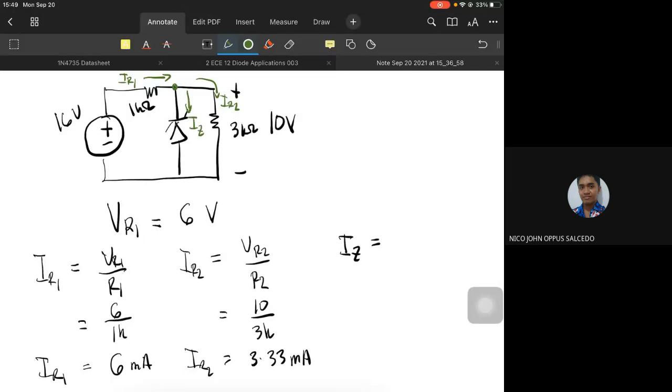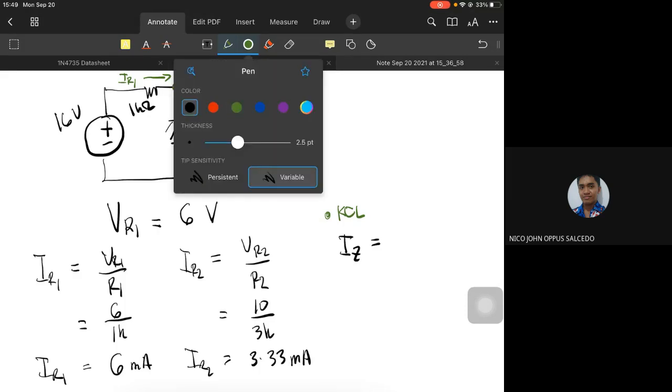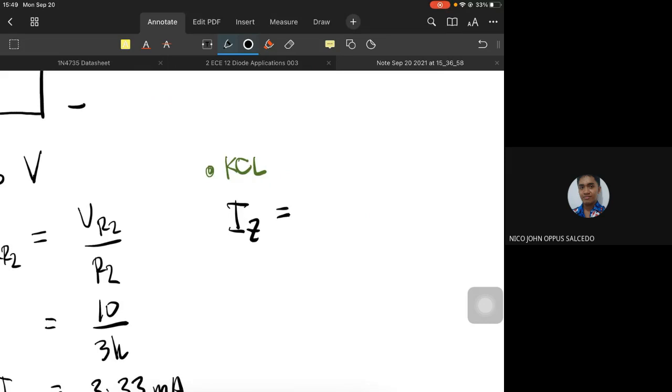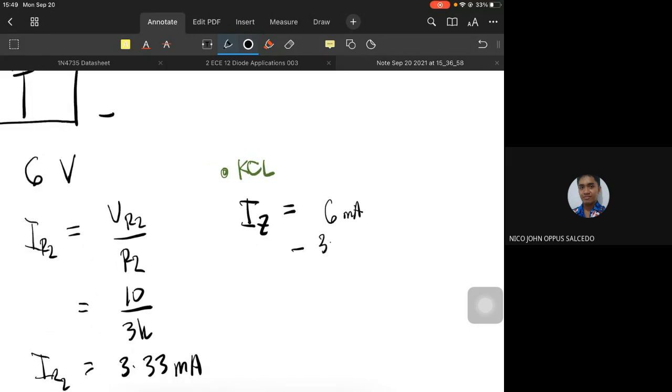So by virtue of KCL, how much is IZ? 2.67 milliamps, sir. Okay, thank you, Nico. So 6 milliamperes minus 3.33 milliamperes is equal to 2.67 milliamperes. Very good.